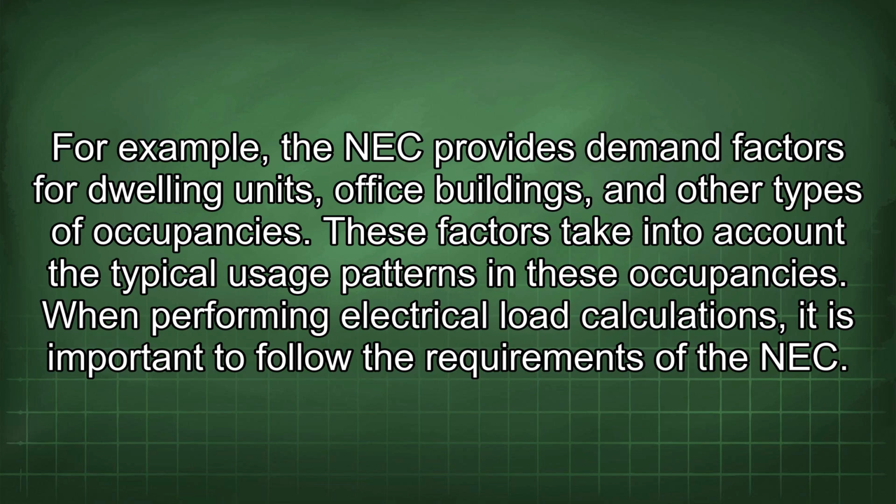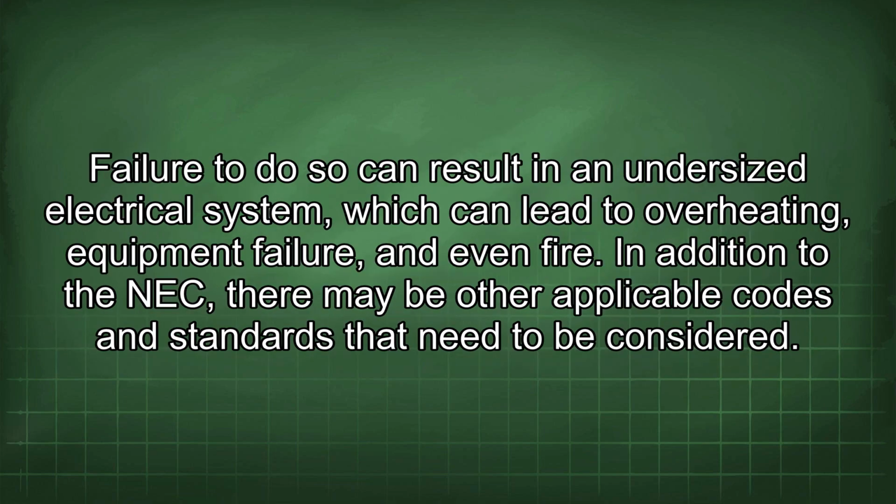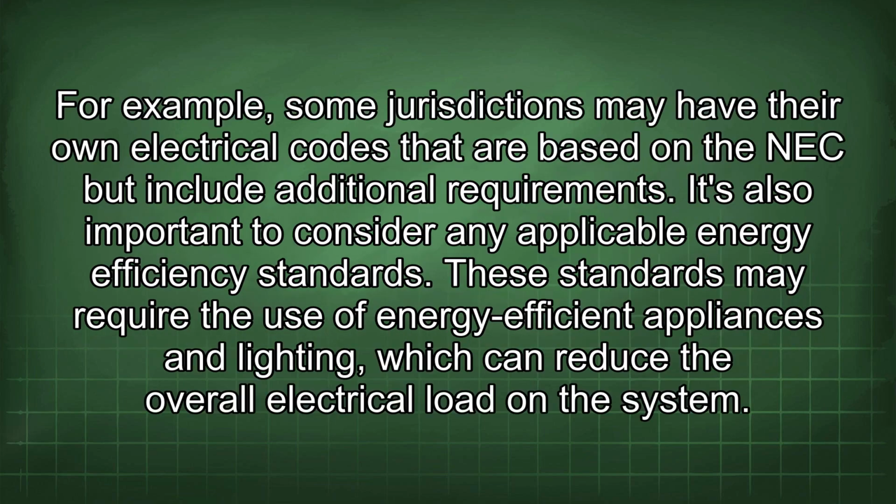When performing electrical load calculations, it is important to follow the requirements of the NEC. Failure to do so can result in an undersized electrical system, which can lead to overheating, equipment failure, and even fire. In addition to the NEC, there may be other applicable codes and standards that need to be considered. For example, some jurisdictions may have their own electrical codes that are based on the NEC but include additional requirements. It's also important to consider any applicable energy efficiency standards. These standards may require the use of energy-efficient appliances and lighting, which can reduce the overall electrical load in the system.